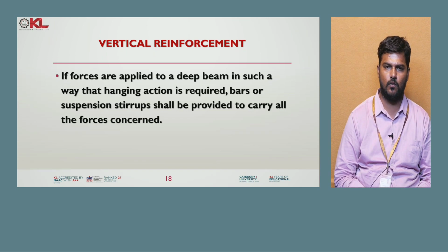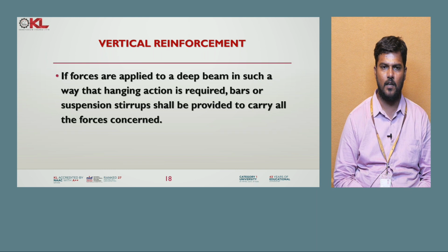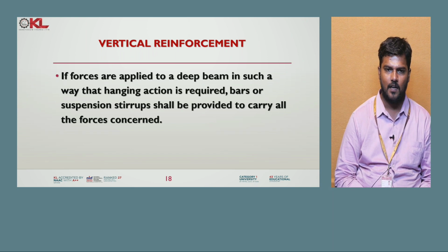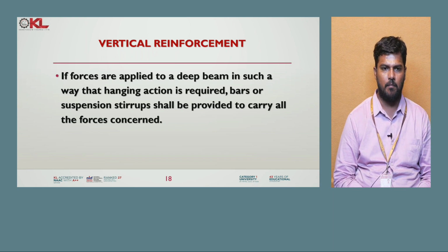So next we are going to our third topic in CO2, that is nothing but the vertical reinforcement. If the forces are applied to a deep beam in such a way that hanging action is required, bars or suspension stirrups shall be provided to carry all the forces that are concerned.